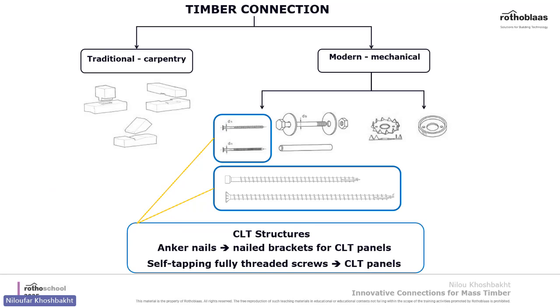So wood connections, we have 2 major categories. We have traditional and mechanical joineries. The traditional joineries utilize classic woodworking methods, as you all know, like mortise and tenon, and these joints gained popularity when CNC technology was introduced, because the CNC technology allows for precise and effective fabrication of these connections. But however, they still cost way more than screws and plates.